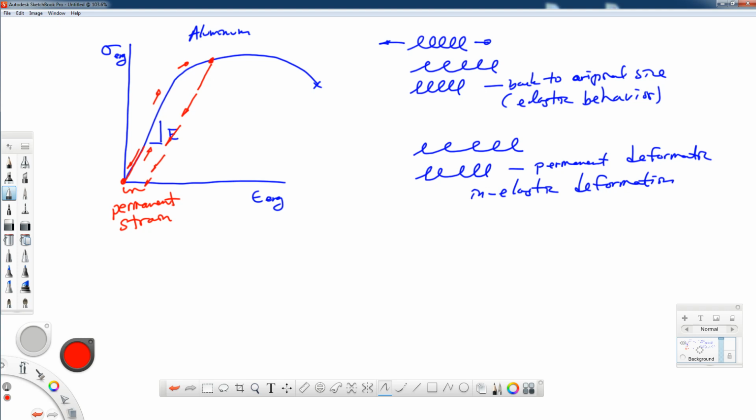Now, it's not very practical in a tension test to load and unload something. When you put it in a tension test, you continue to stretch it out, and the forces keep increasing until they hit the necking point of the material, where then it starts to decrease. We don't ever unload it and measure the dimensions and say, okay, it's okay here, but it's just, I don't know, 0.001 millimeters longer, now we have permanent deformation. We don't do it that way. But we do something called a 0.2% offset yield stress, and we can get into those details. I do teach a class in mechanics of materials and talk about laboratory results for the mechanics of materials lab. And I do have other classes and videos where I go into that level of detail as to when we have permanent deformation and so forth.